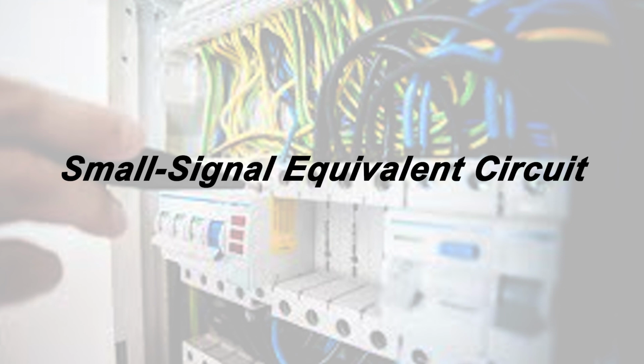In a small signal model, each transistor is represented as a small signal equivalent circuit. For a bipolar junction transistor, this often includes the transistor's hybrid pi model, while for a field effect transistor it includes a small signal model like the transconductance model. The AC analysis includes transistor parameters like transconductance gm and output conductance go.